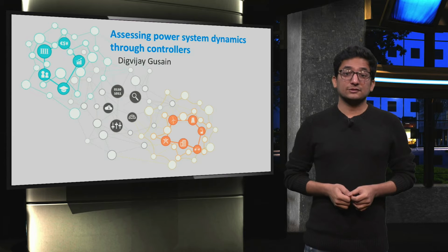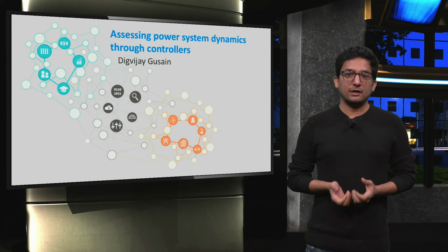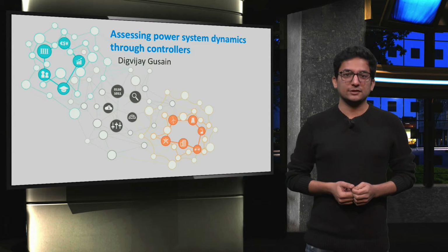The system that was created for the previous exercise is an uncontrolled system. You saw the effect of a load step event on such a system. To reduce that voltage imbalance, we have to introduce a control mechanism. Power plants generally employ automatic voltage regulators to control the generator voltage in an event of voltage change.